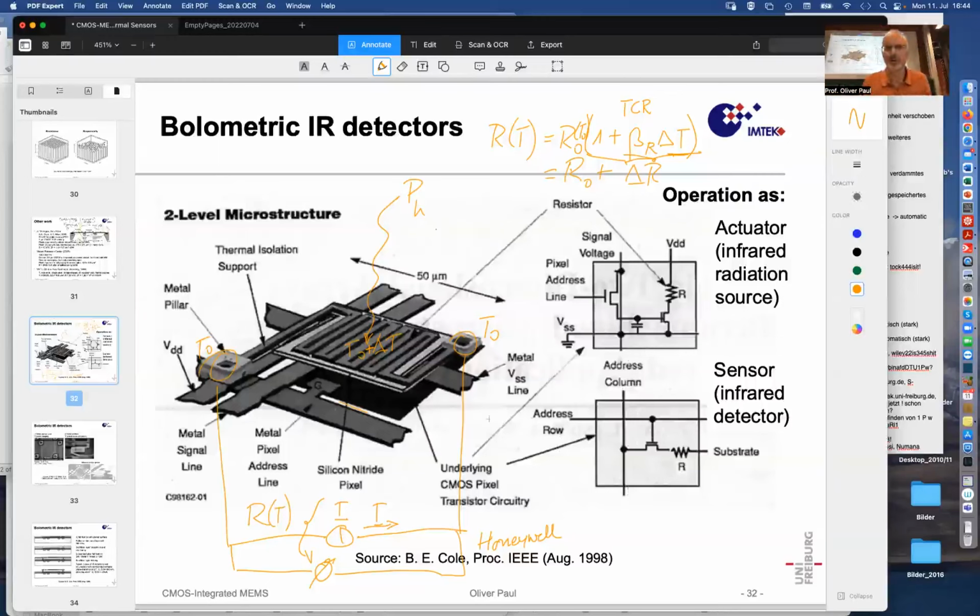And if this transistor is switched on, among all the pixels that are hooked up to that same line, they will all be switched on, but only the pixel at this location receives a column signal of, let's say, a volt to let a current flow through so that its resistance can be measured.